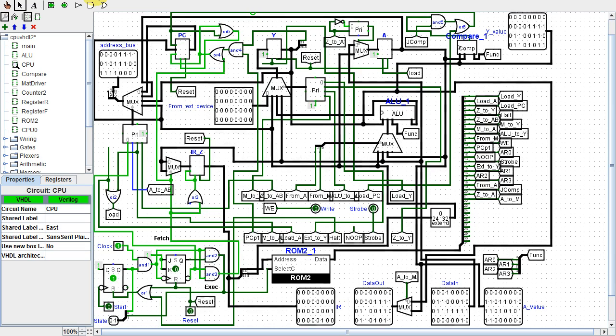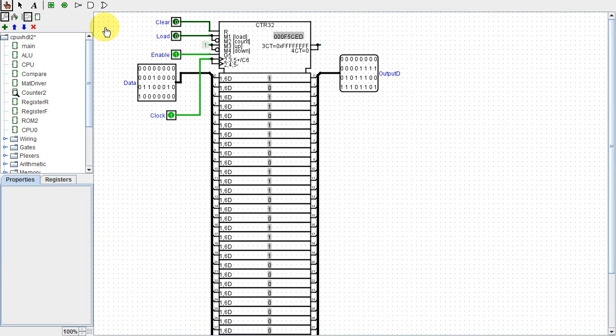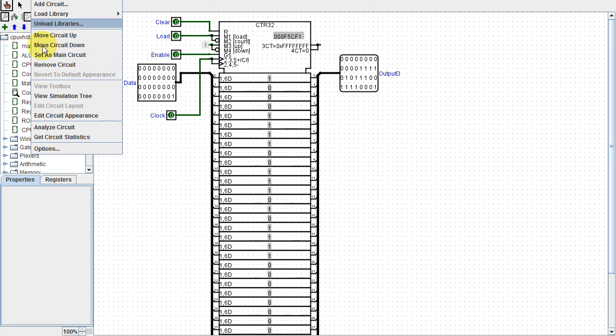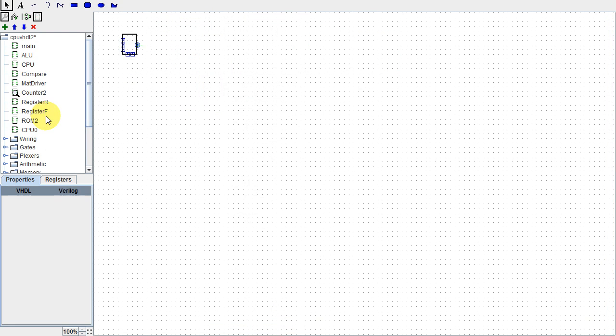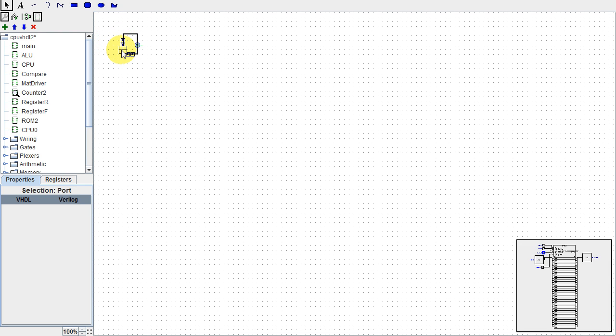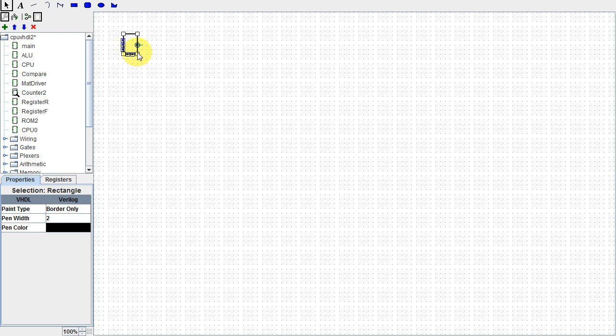I needed to put some of Evolution's memory components in subcircuits, since they take up way too much space. You can edit the circuit's appearance to make it look as close as possible to original Logisim's version of the component, making sure to put the ports in the same spots. Squares for inputs, circles for outputs. Note the diagram in the lower right-hand corner showing what the selected port indicator represents. If you want to get fancy, you can add text, lines, circles, etc.